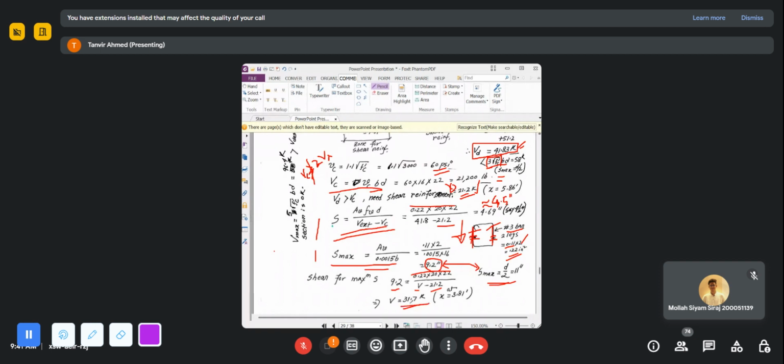31.7. So from this shear force downward, that means when you have a shear force of this value or less, you can provide the maximum spacing for your shear reinforcement.